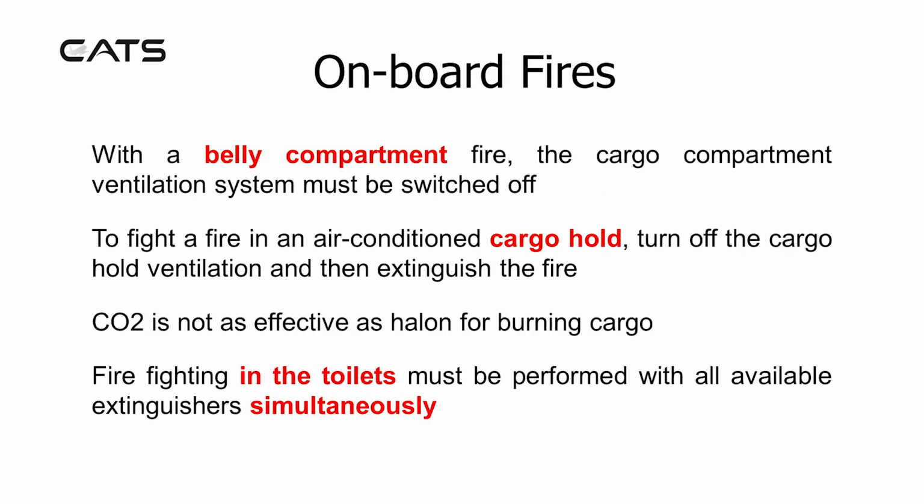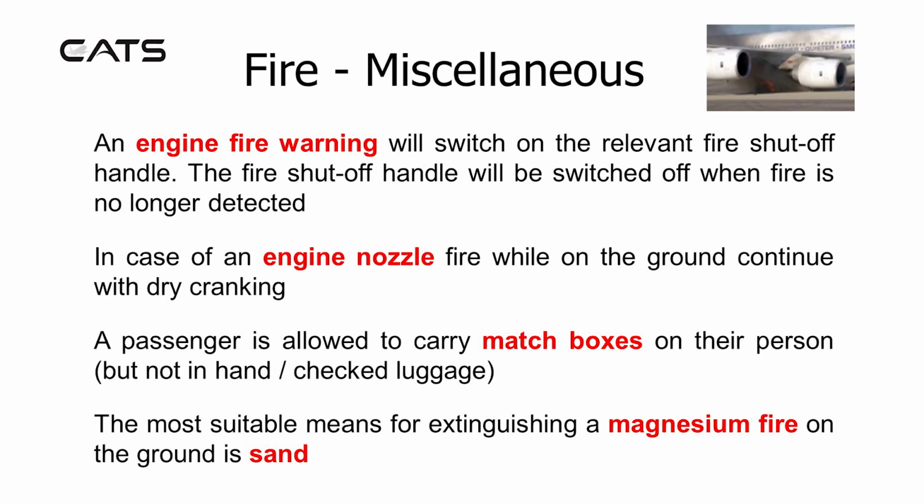With a belly compartment fire, the cargo compartment ventilation system must be switched off. To fight a fire in an air-conditioned cargo hold, turn off the cargo hold ventilation and then extinguish the fire. CO2 is not as effective as halon for burning cargo. Firefighting in the toilets must be performed with all available extinguishers simultaneously. An engine fire warning will switch on the relevant fire shut-off handle. The fire shut-off handle will be switched off when the fire is no longer detected.